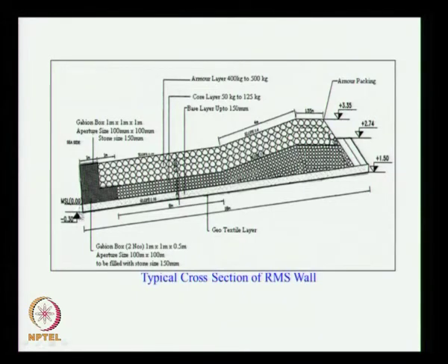So part of the breakwater will be submerged during high tide, but during low tide there will not be any water, so it can facilitate construction. The point is clear now. When building from the shoreline up to the low water level, you have a certain duration in a day when it is without water, so you can do the work.